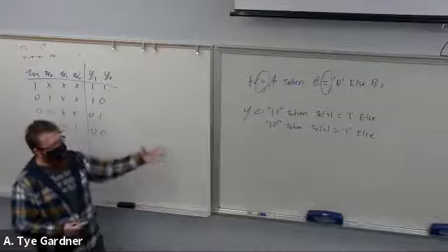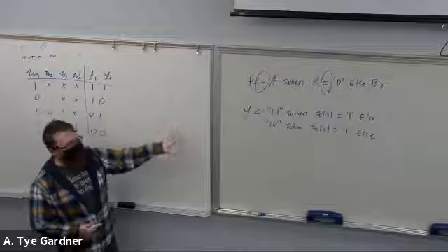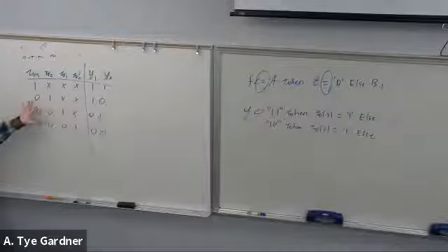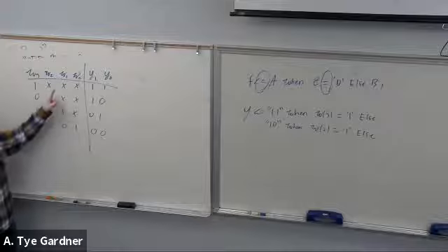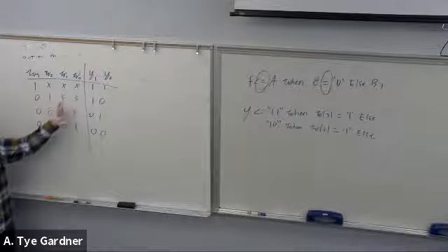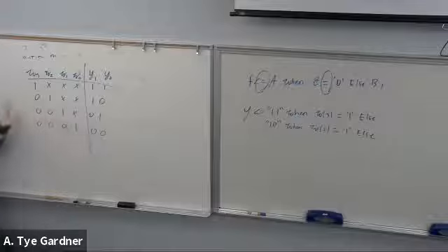Now, another reason that we use the conditional assignment on the priority encoder, we like priority encoders, is because these don't cares, while hard to design logic for yourself unless you're writing VHDL code, are actually really easy to design whatever's upstream from it, right?